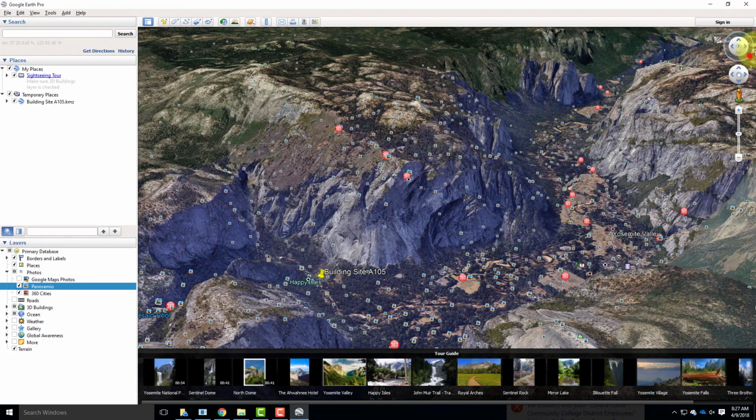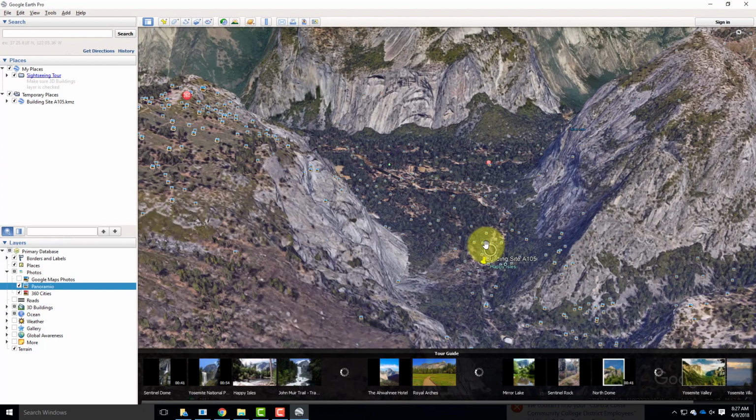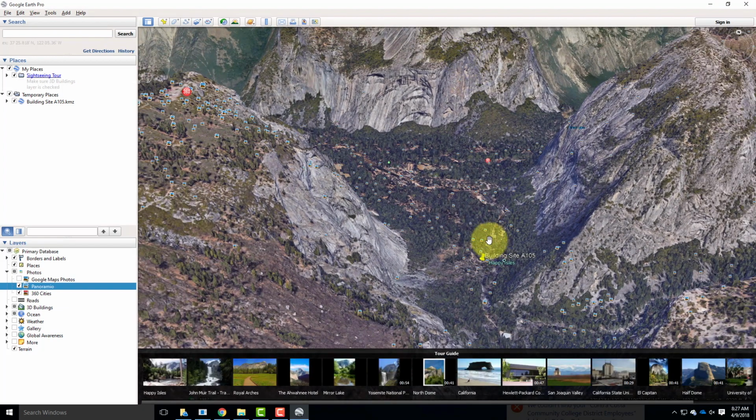When we start thinking about the building site, let me flip myself back around here a little bit. So right here, I'm looking north. So all the windows that would be on the face of the building looking down the canyon would be north windows. So I don't have to worry too much about direct sunlight coming into those windows. I can have lots of glass without a problem. I'm not going to get big heat gain on that.